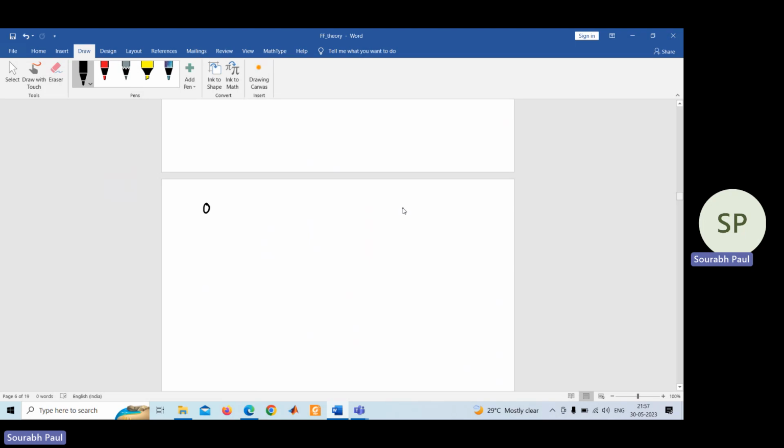That is well known because you know the formula 2 to the power n equals the number of states. So in this problem, the number of states is 8 and you need to determine the value of n, that is nothing but 3. This decides the number of bits you need to use to represent each state. That n is the number of bits required to represent each of the states. You need to understand that. Okay. So how many bits do you need to use? 3 bits.